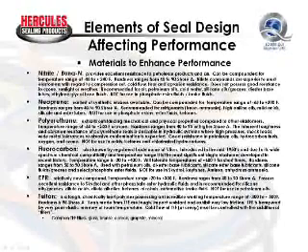Polyurethane exhibits outstanding mechanical and physical properties compared to other elastomers. Temperature range can be from minus 65 to 100, and there are actually some compounds that will range as high as 275 degrees. Hardness can be from 40 to 95 on the Shore A scale, and its inherent toughness and abrasion resistance is desirable in hydraulic systems for high pressures and shock loads. You can allow for larger metal tolerances with a urethane seal than you can with a nitrile seal at higher pressures.